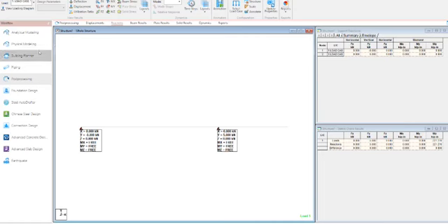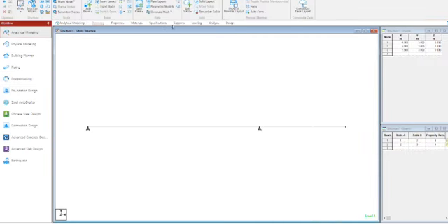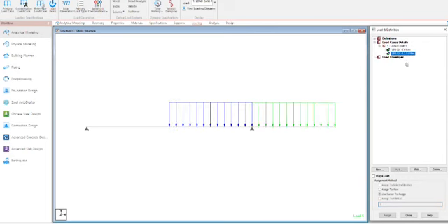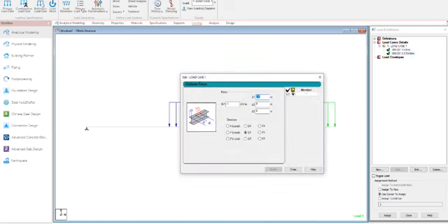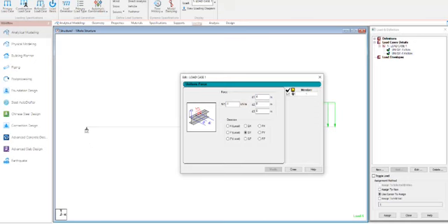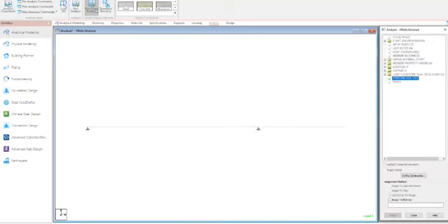So now we will see these changes. If we change it, instead of a 2.5 equivalent value, you are making it 4 meter. That means only 1 meter is going to act. That means the reaction should come now in negative. Instead of upward reaction, downward reaction should come. We will see how it comes.